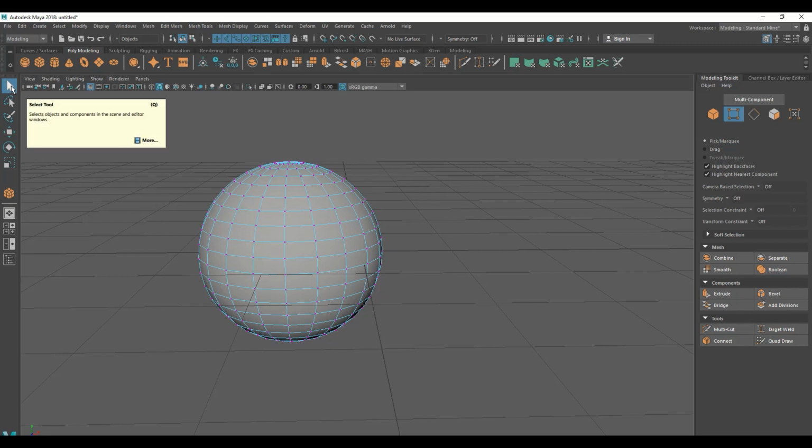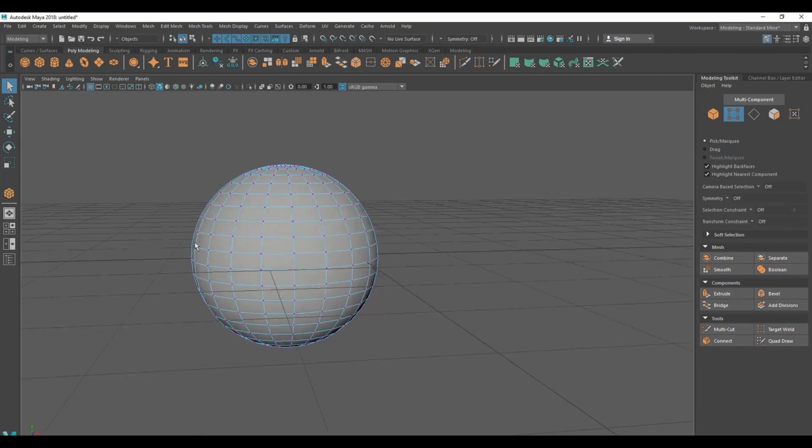So this is the select tool, and now let me tell you about the lasso select tool. The difference between these two tools is that when you use the select tool, you get a square selection shape. The problem with this is you cannot select very complex shapes. Let's say I just want to select this side area till here; I cannot select it without selecting these things.